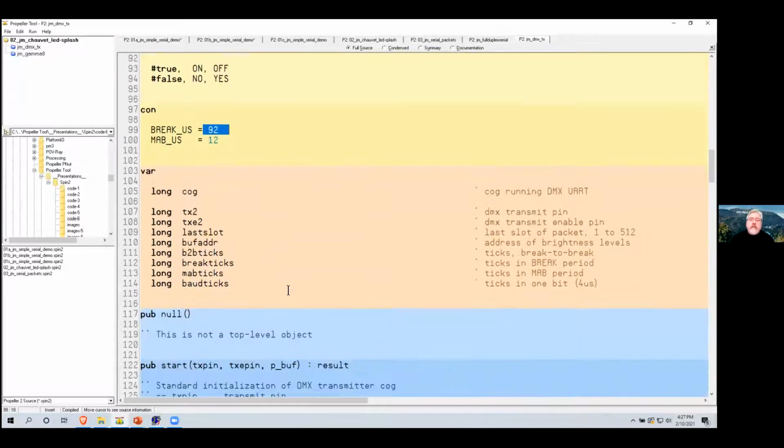Again, the DMX standard is you're sending out 513 bytes. So if you're going to experiment with DMX, which is fun, I have a DMX fixture sitting here that I'm going to turn on. It's plugged in here, so I don't know if it'll show. I can't reach it with the cord. You have to check to make sure it will tolerate a shorter than standard universe, because the spec says 513.